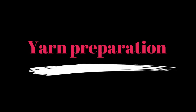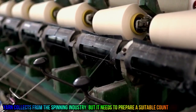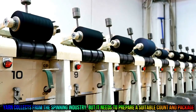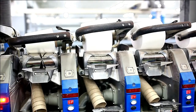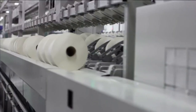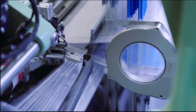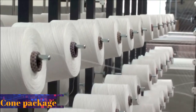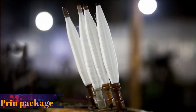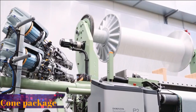Yarn preparation. Yarn is collected from the spinning industry, but it needs to be prepared in a suitable count and package. Winding. Winding is required for preparing a suitable yarn package. We know that in the weaving process, two sets of yarn are used: warp and weft yarn. Warp yarn is wound into a cone package, but weft yarn is wound into a pirn package for a conventional loom and a cone package for a modern loom.